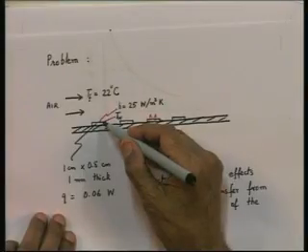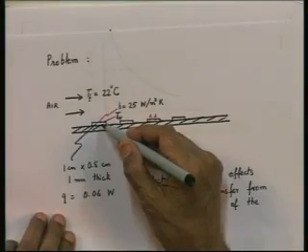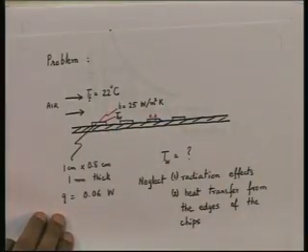The moment we reach surface temperatures like 90 or 100, that is not a good sign, because a high surface temperature means a still higher temperature inside the chip. If the surface is 97, inside the chip where the heat is being generated, the temperature will be another 10 or 15 degrees centigrade more. So, a temperature like 50 or 60 may be acceptable; a temperature like 97 would probably not be acceptable at all.